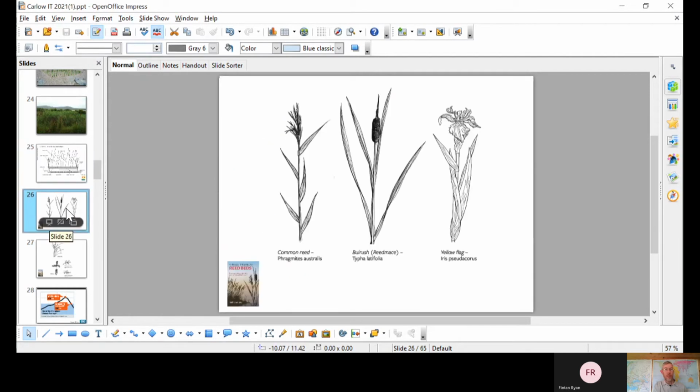So the plants that are used, the common reed is the one that's most commonly used in the vertical flow and horizontal flow reed bed systems. And then all of them are actually used in the soil-based constructed wetlands. So soil-based wetlands have a greater diversity of plants than gravel reed beds. This is a particularly deep-rooted plant, so it's particularly good for the gravel systems.